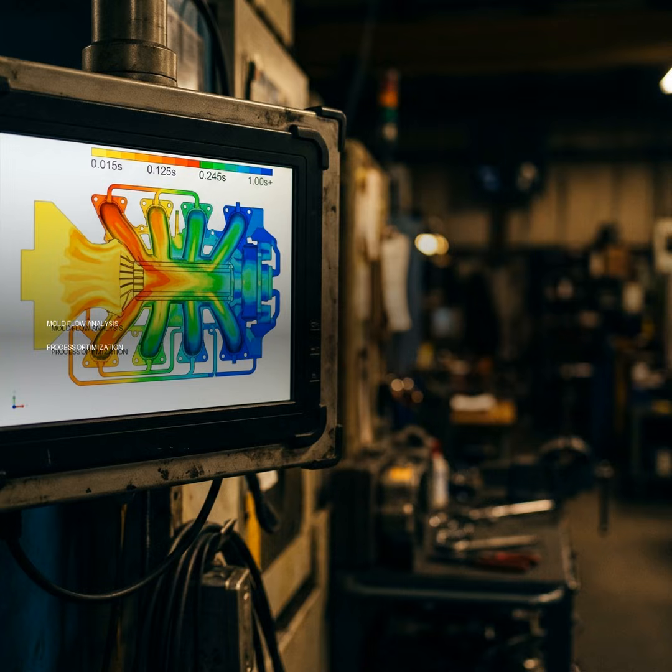Max injection pressure, that tells you if your machine can even handle it, I guess? Precisely, and the clamping tonnage too, which indicates the force needed to keep the mold closed. You'll see max and min melt front temperatures, giving you insight into the material's thermal behavior. Then there's the material data section: density, melt temperature, mold temperature, melt flow index. All essential for understanding the material's characteristics.